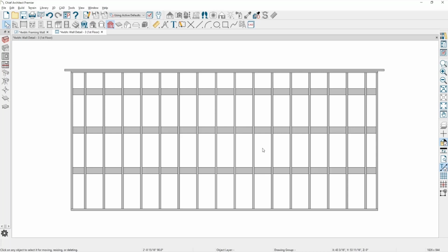Yes, yeah. We have what we call our bridging nogs, and they're usually flat. They just stiffen up the studs basically, because quite often we're not putting plywood on the outside. So it is a bit of a hassle for the electrician. He's got to drill through those to put his wiring in, but that's quite common in New Zealand to have rows of nogs or bridging.